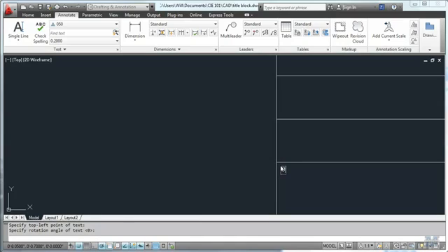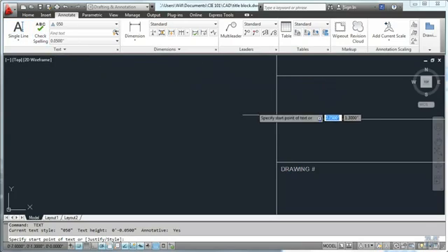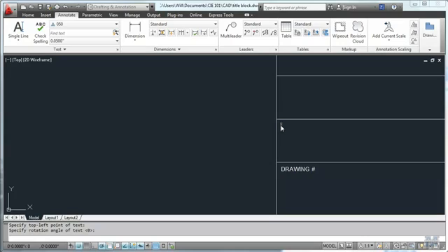So caps lock on. Drawing number. So that's going to be that label. I hit enter, it goes down one line, hit enter one more time, and that finishes putting that piece of text in. We can do it again, hit the space bar, and instead of typing justify, I'll just type TL, and that justifies me to top left. I go to the same thing right there, hit enter on 0, and that's going to be scale. Enter a couple of times.